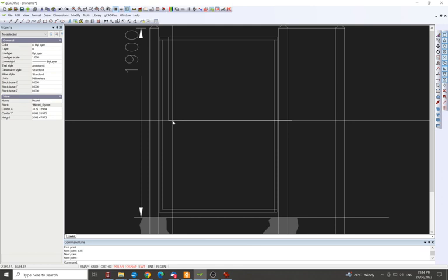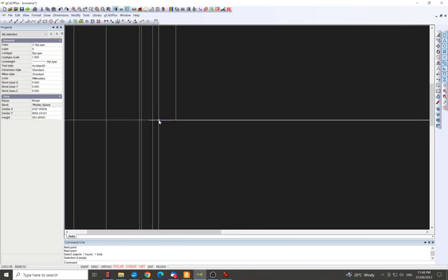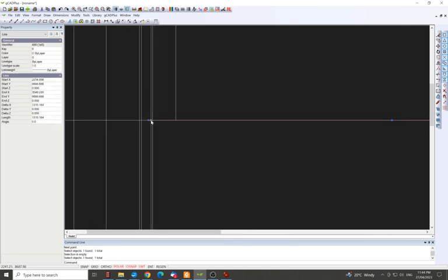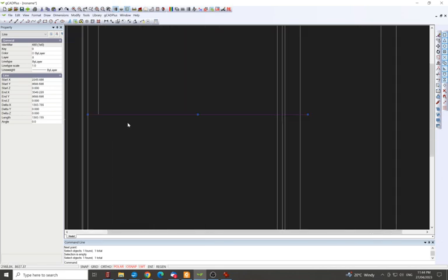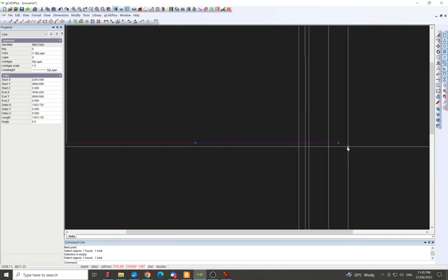So I'm going to go to there. I'll drag this. What I tend to do, if I try to drag onto that line and connect it directly, I can never get polar tracking correct. It won't polar track sitting on that line. But if I go past it, it polar tracks. So I go past it, polar track it, and then I bring it back and snap it on, because that way it stays straight. That's just how I do it. I just find that works.